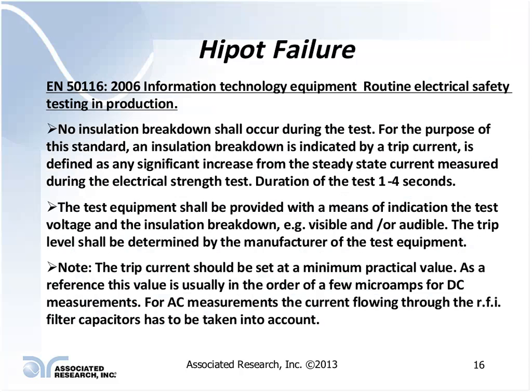Why is that important? Many a times, if you look at some of the old analog Hipot testers that were out in the market, one thing you have to consider is if you're only doing a 1-second test, typical response time of the metering network is anywhere from 2 to 3 seconds.